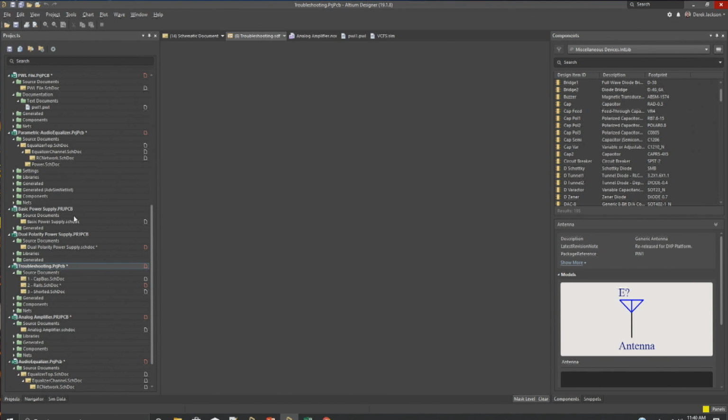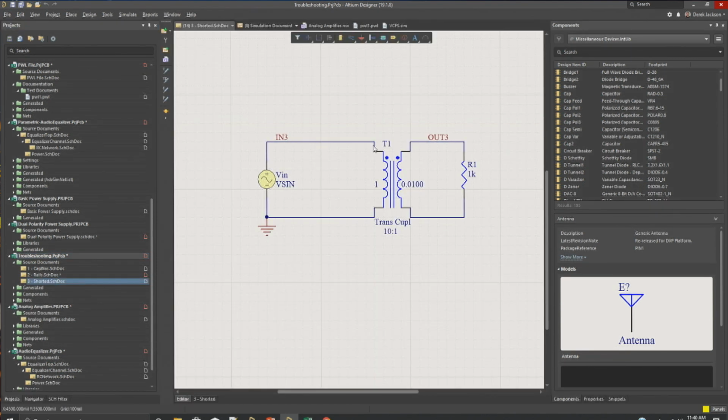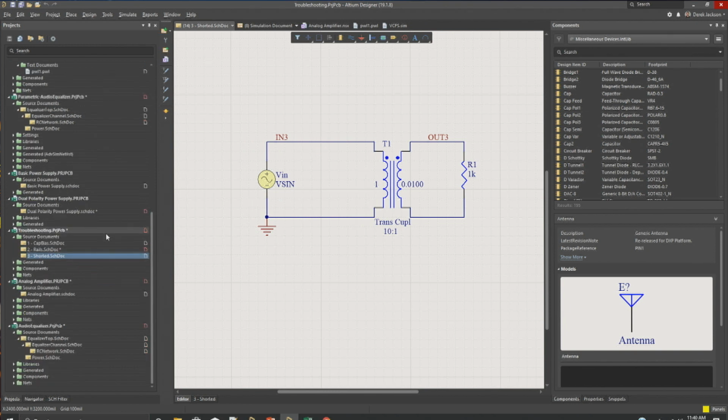So one way to resolve that would be to put a series resistor in here, or if you take the SPICE class, it shows you how to build an inline resistor where you can just netlist it in. You just manipulate the template, put in a resistor, and manipulate the pins. You can create extra nodes and create different virtual devices within that.